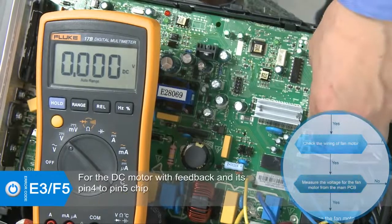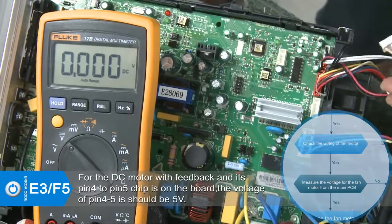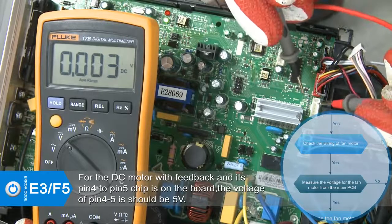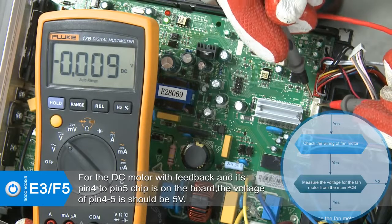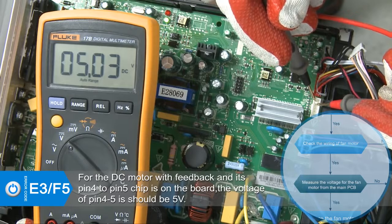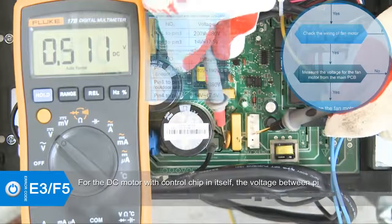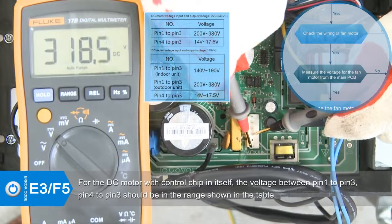Examination for main PCB board. DC motor with feedback, and its control chip is on the board. Turn the power on. When the unit is in standby mode, measure the voltage of pin 4 to 5 in the feedback signal connector.